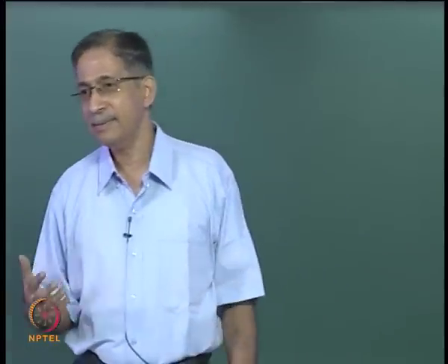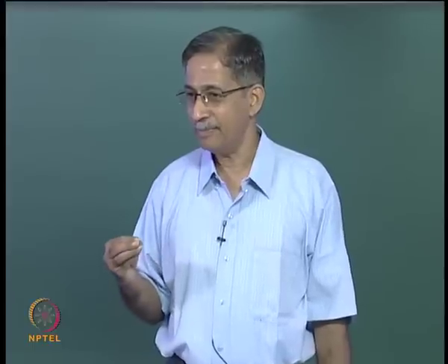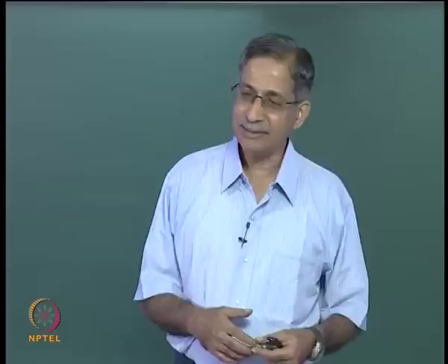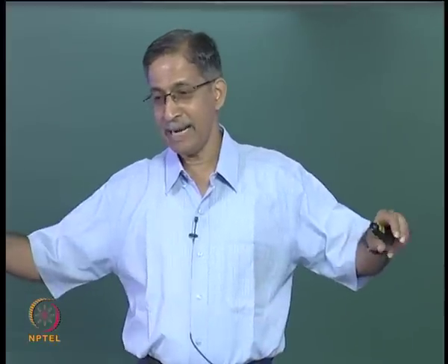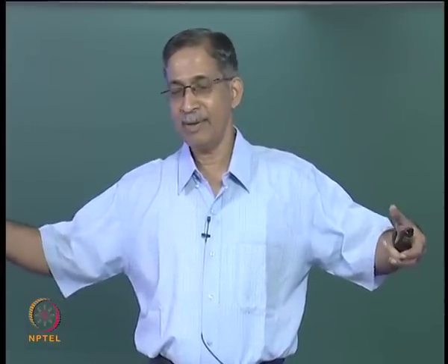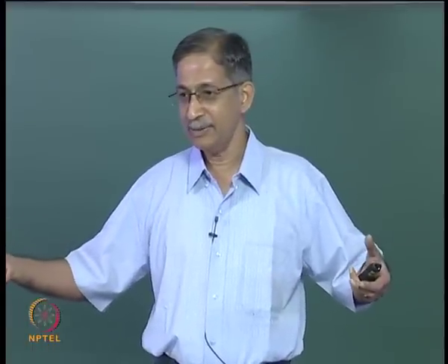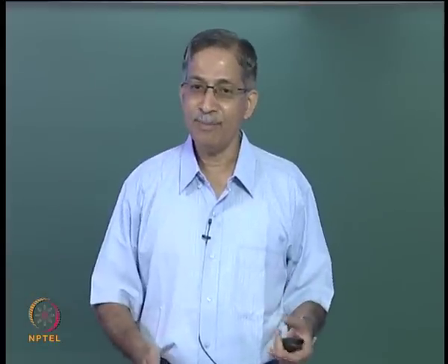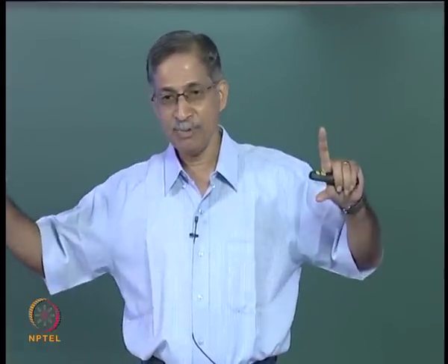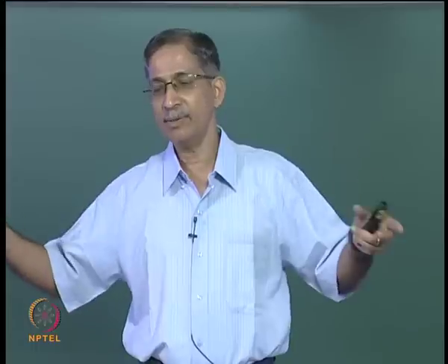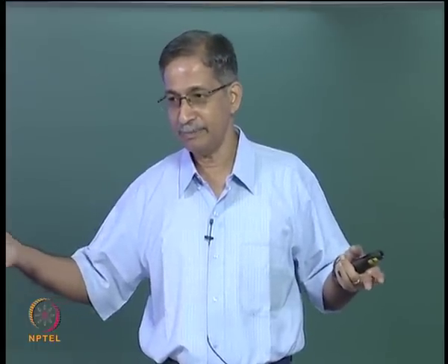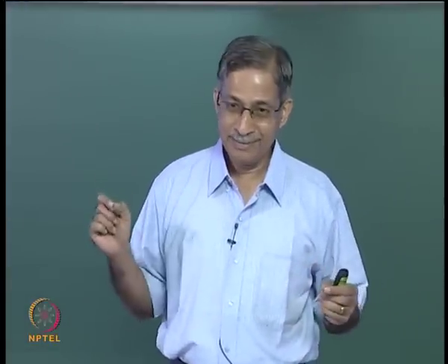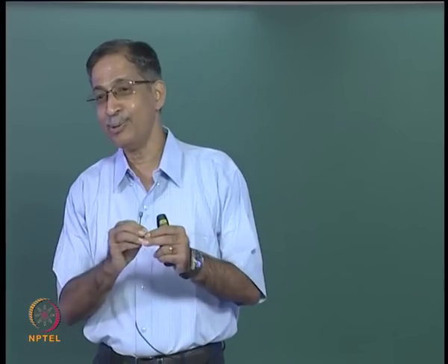So I want you to think, you have to finally bring it to bending moments, right. In the slope deflection method of analysis, we were happy with the end moments being unknown, and we write the end moments in terms of slopes and deflections, and we get the end moments, and then we get the moment in between at any point by interpolating the end moments, right, because your beam is reduced to a simply supported beam. Agreed? So what is the variation of bending moment? That is linear, as long as you do not have intermediate loads.